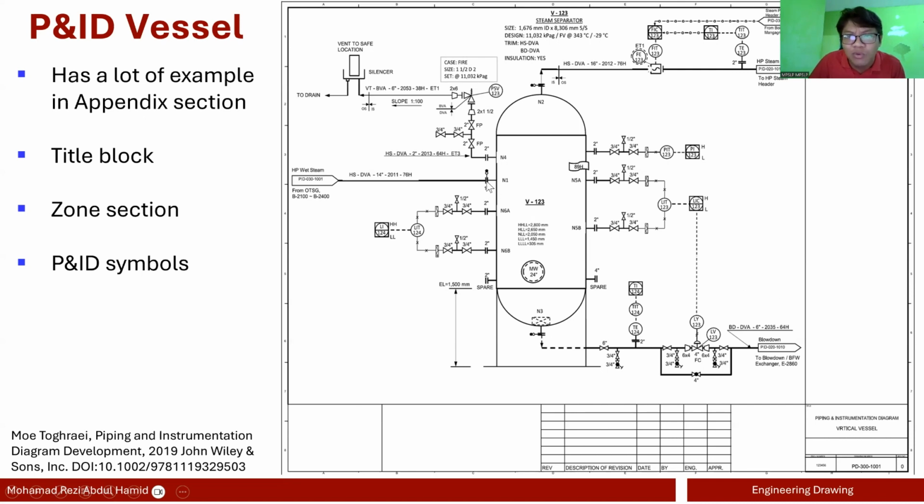One thing that I would like to highlight here is that these are flanges. These symbols, we have filled circles and open circles, black circles and white circles. These are called spectacle blinds. A spectacle blind is like a number 8 ring, where one circle of the 8 is open and the other circle of the 8 does not have a hole. Basically, if this line is being used, your spectacle blind will be active.